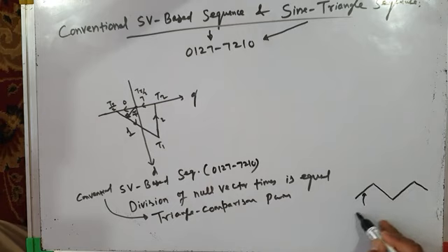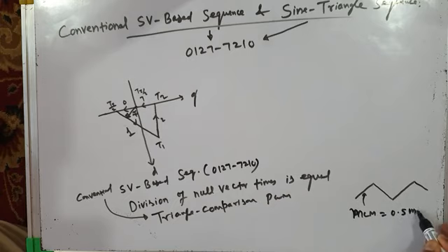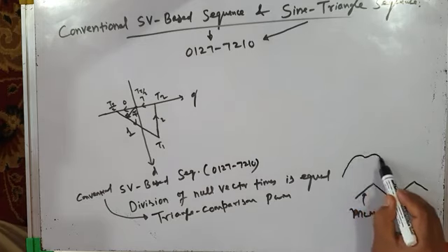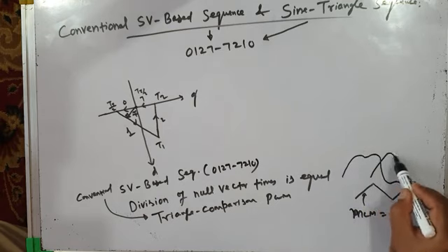This is our common mode signal, which is MCM equal to, if you remember, 0.5 M mid. If you are able to generate a common mode signal whose amplitude value is equal to 0.5 M mid and add that common mode signal to 3 sinusoidal modulating waves, we get our modified modulating waves, something like this.